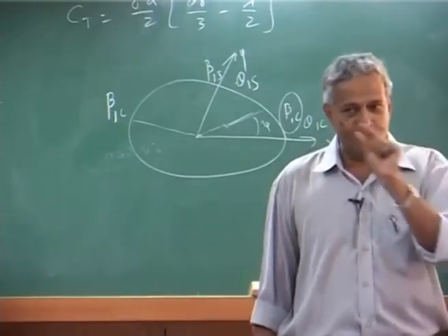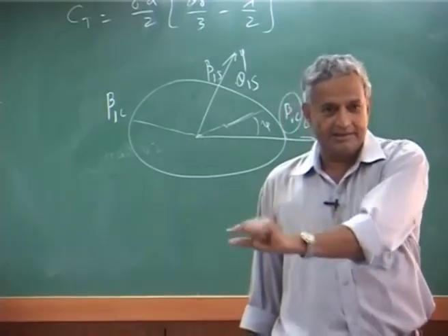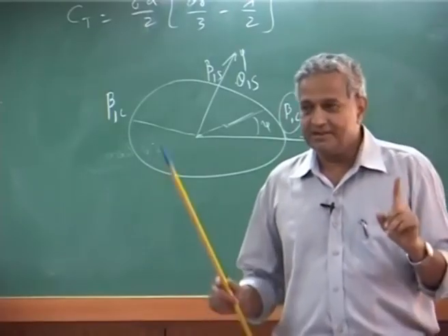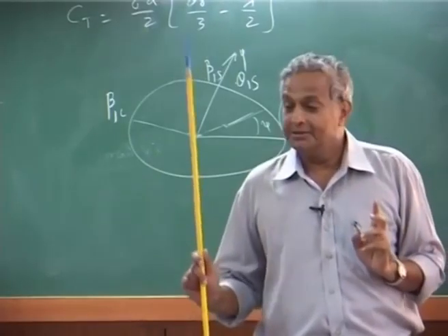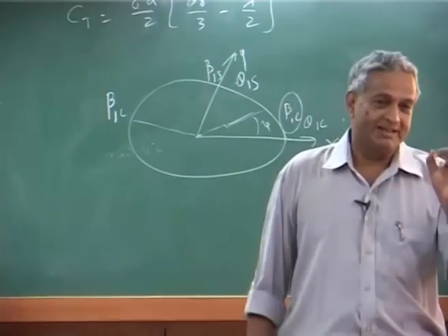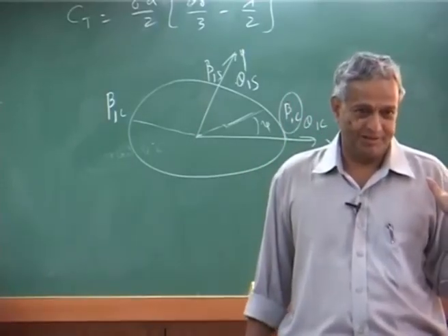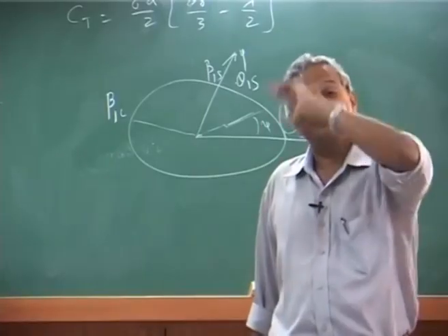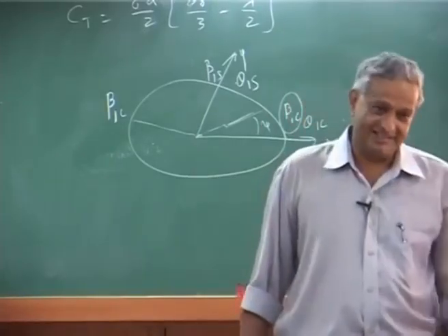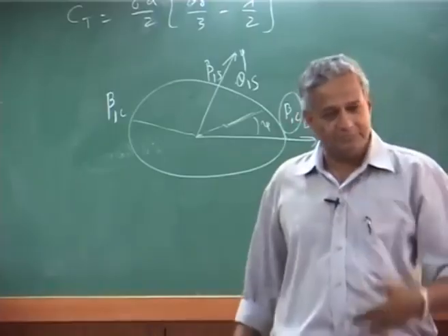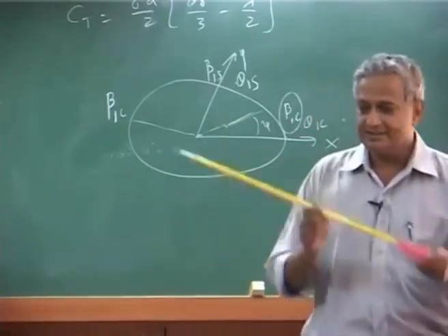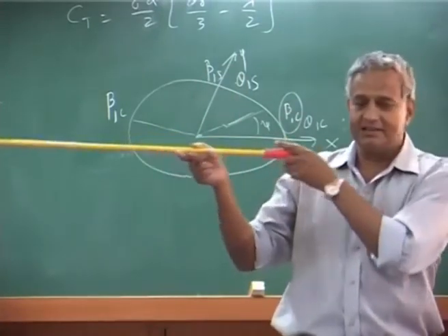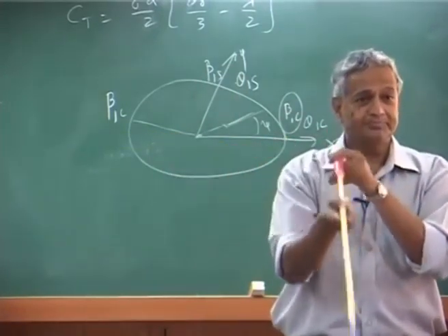That means, when the input frequency is equal to the natural frequency, the phase difference between input and output is 90 degree. That means, if you give an input now, its effect will be shown after 90 degree, then you convert it into time. Here we know that 90 degree is basically, in this disc, if I change my pitch angle here, the response will be here.